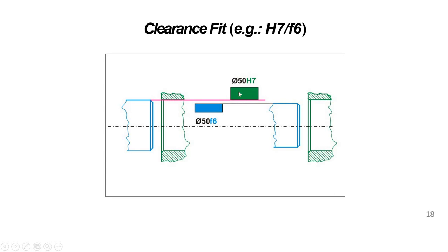Okay, so you can see by these 2 figures that the hole with the minimum size also has a size more than the maximum size or maximum limit of the shaft. So we can have a definition of clearance fit as the type of fit in which the maximum size of shaft is always smaller than that of the minimum limit of the hole.